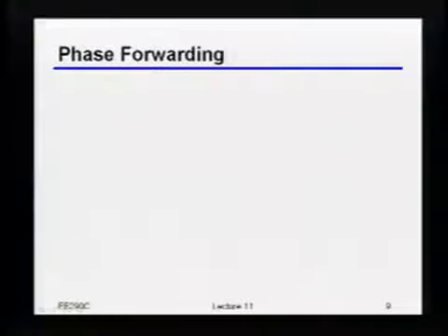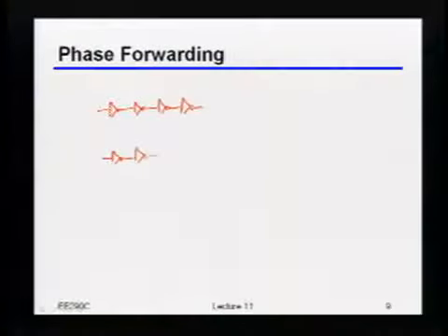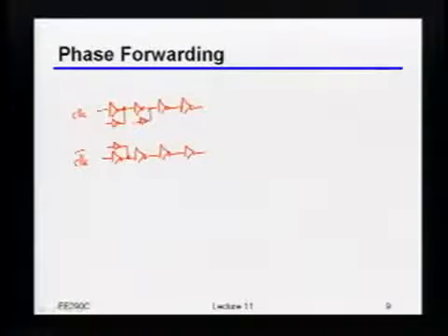So let's take our chain of inverters that we used to have, something that looks like that. And let's imagine that somehow I have clock and clock bar right here. Conceptually, what we were doing before was adding another inverter in parallel with that main inverter. At every one of those stages, we had another inverter that was going to enforce that we actually got the right differential condition.